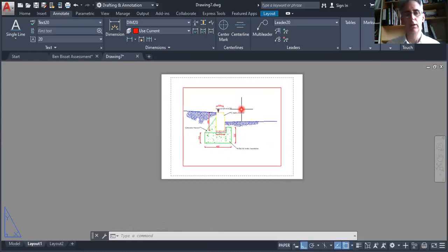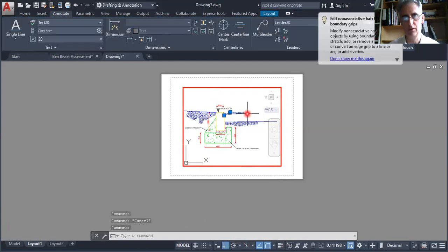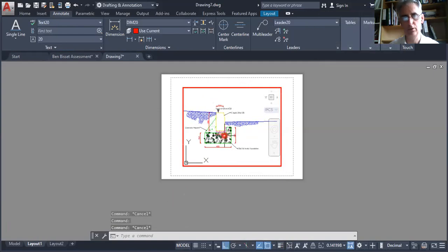Okay, so at the moment we are in a thing called paperspace. Now, paperspace is where you're basically able to edit what's going across your paper. Now, I could edit my model by clicking on here and it comes back into model space. So if you see a big thick line around your viewport, that means you can actually go in there and edit the drawing that you've just created. If you see that, I'm just clicking on the text. Okay, so basically I can do just about anything I want to do with that model that I did when it was shown as a black screen.